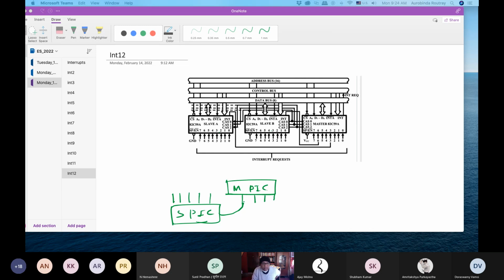Input, yes, sir. Look at this. The edge sense circuit is reset, which means that following initialization, an interrupt request input must make a low to high transition to generate an interrupt. The interrupt mask register is cleared. IR7. So these are called initialization command words.